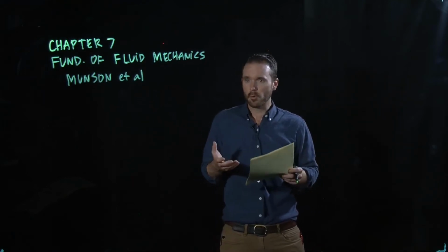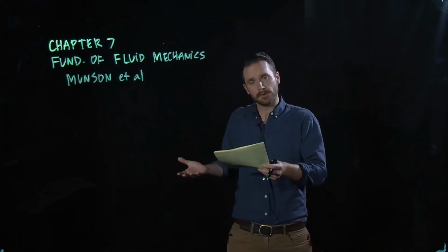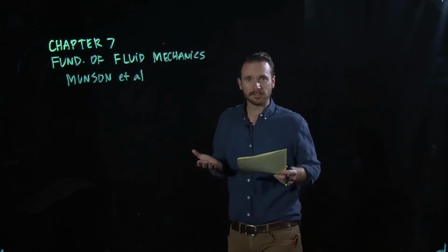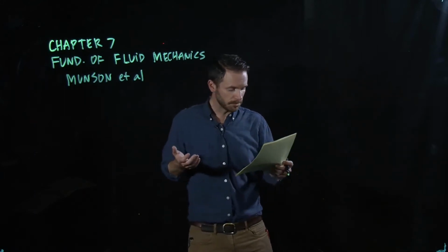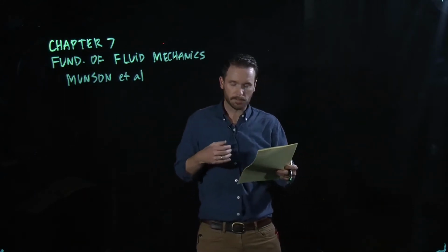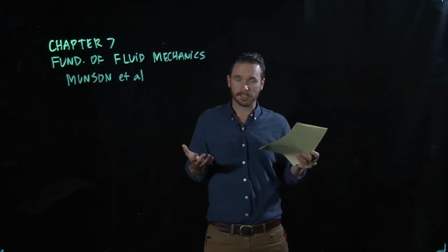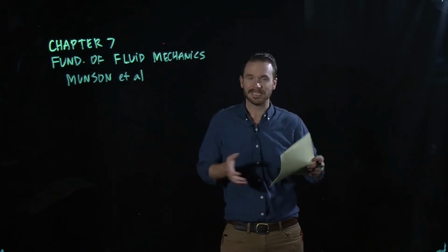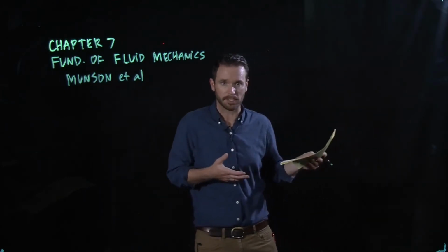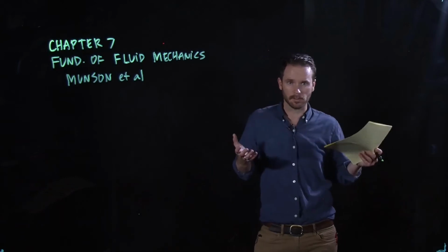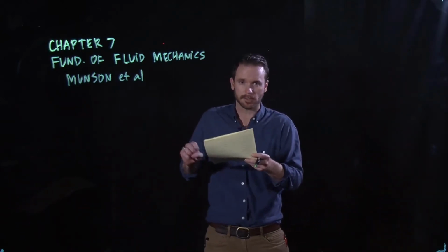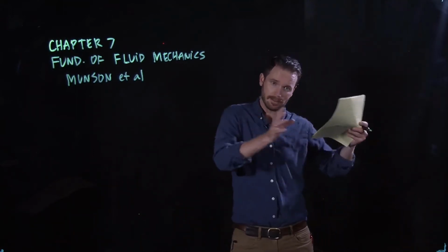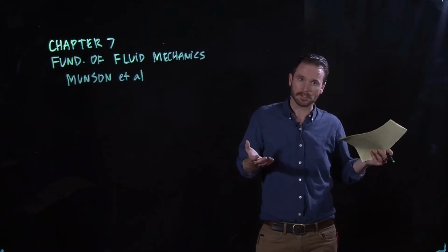And furthermore, we want to be able to correlate the data that we may get in an experiment to that in a real-world situation, right? And so this concept is called similitude. Similitude is when measurements made on one system, typically called a model, that is used in a lab, can be used to describe behavior of other systems outside the lab. So say a real-world application. For instance, if we're using a wind tunnel, we can take measurements on a small model-sized car, and we want to be able to take that data, say drag force, and extend that to a real situation where we had a production vehicle.